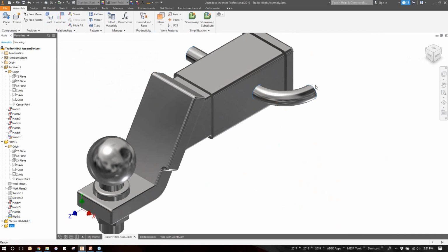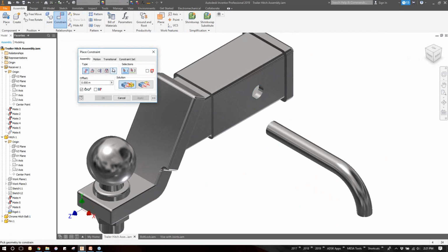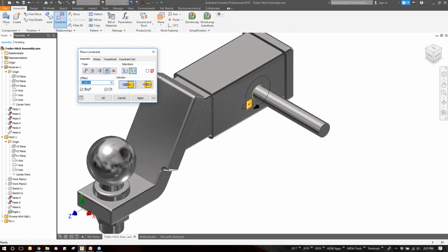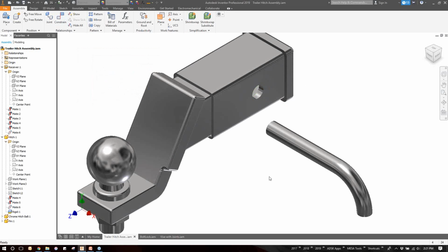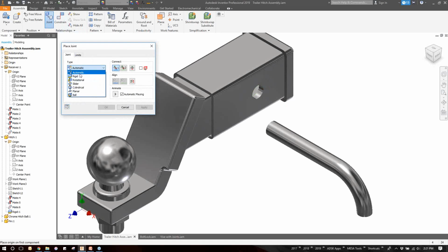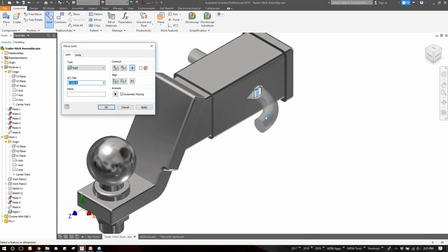A situation like a bolt or a nut, that lock degree of freedom on the insert type is a pretty nice little trick that they've added into it. So take a look for that checkbox once you get into the 2019 software. In our situation, because clicking that checkbox turned it to the side, I'm going to switch back over to a joint type, rigid type. I'm going to click those same selections. I'm going to place that in there.